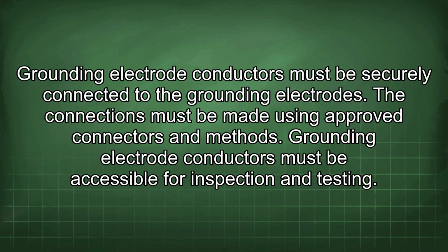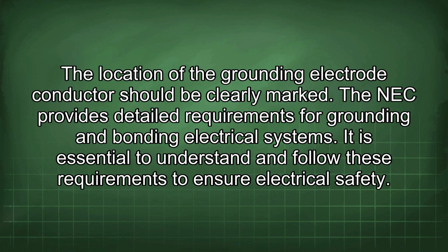Grounding electrode conductors must be securely connected to the grounding electrodes. The connections must be made using approved connectors and methods. Grounding electrode conductors must be accessible for inspection and testing. The location of the grounding electrode conductor should be clearly marked.